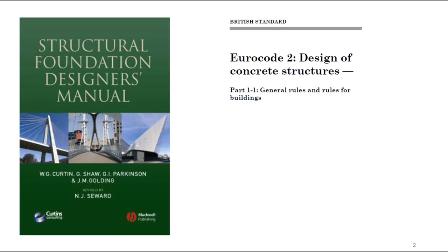It's because we use that simplified approach, which is valid for semi-flexible raft slabs. And this is actually the case for relatively thin ground-bearing slabs, which are used in domestic buildings or garages. If you would like to design or check a raft in multi-story concrete frame buildings, it's not the correct software.